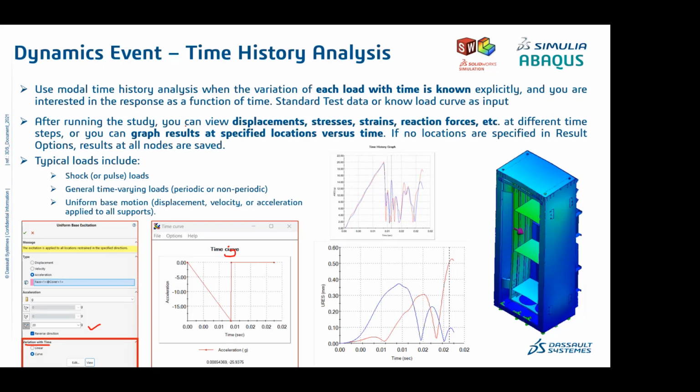After running this study, you will be getting the displacement, the stresses, strains, and reaction force at different time plots across your dynamic event. This will significantly help you evaluate how your model is going to behave across the dynamic event, rather than just considering the static event. The typical loading conditions, as I told, might be a shock or pulse load, or a general time-varying load, and uniform base excitation with respect to displacement, velocity and acceleration. If you have these loading conditions, you can put them straight into your dynamic event and see the highest stresses and displacement across the time duration.